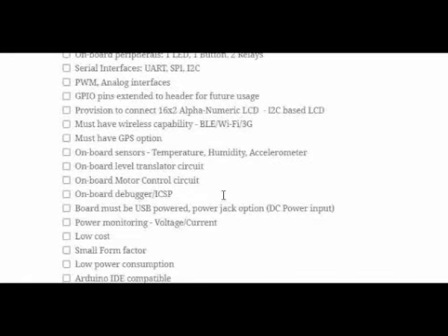So this one requirement, you might need to have 4 UART interfaces, which can be handled in the design. Okay, so not reading all of them at a time, or there can be some arrangement that can be made in the design. So it's not technically difficult. And then onboard sensors, temperature, humidity, accelerometer, all these will have I2C interface, so definitely possible. And then onboard level translator circuit, yeah, this can be used.